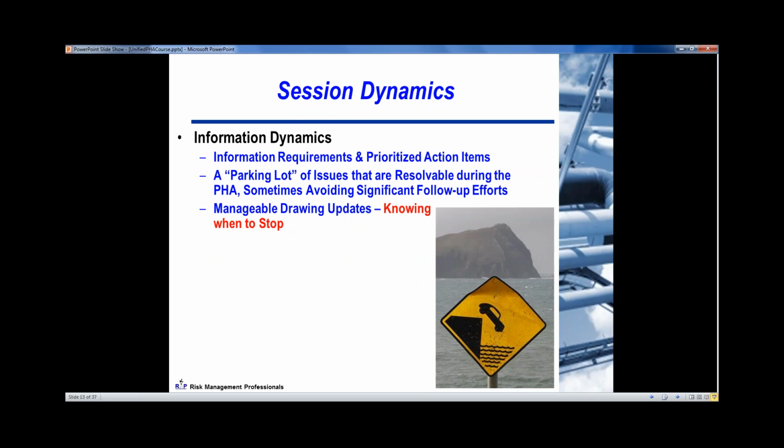Another thing about session dynamics is managing drawing updates. For all of those of you who've done a HAZOP study during a design, you realize that the design is a moving target. If you can make manageable changes on the drawings that the team understands, then basically you've got a core of being able to have a good HAZOP study.